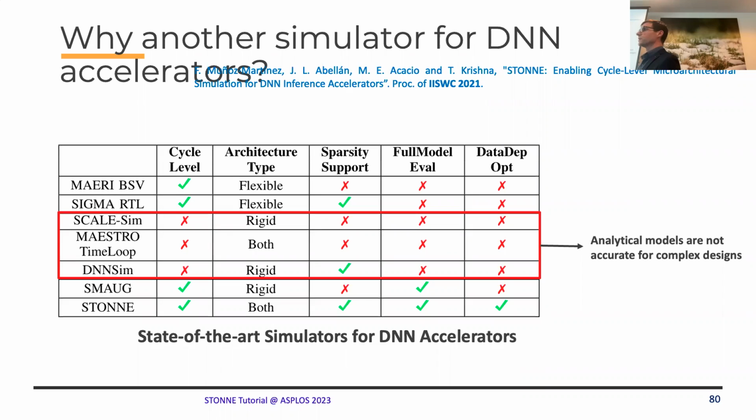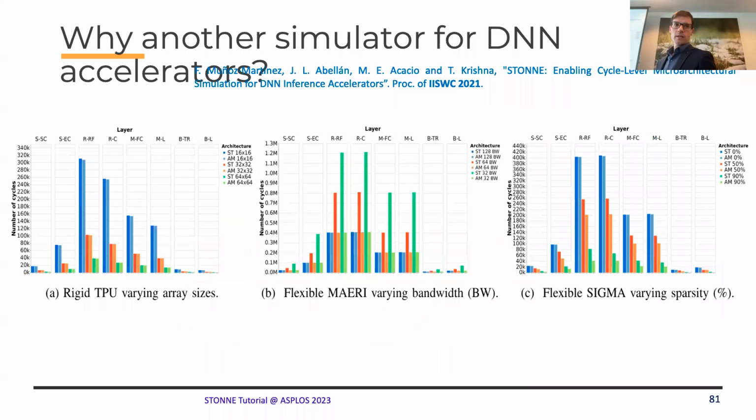Or when you want to understand stalls in the compute pipeline, that happen, for example, when you cannot read an element. So analytical models are not useful there. They are useful if you want to provide some Pareto optimal parameter configuration for the accelerators, but when you deep dive, we observe that analytical models lag far behind a cycle accurate, precise runtime modeling of the DNN workload. So this is what we try to motivate here: the comparison of a cycle level simulator against an analytical model.